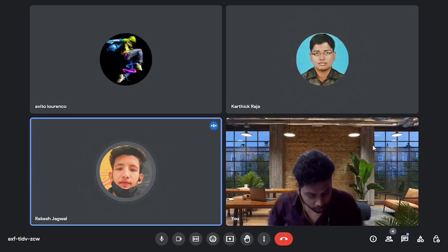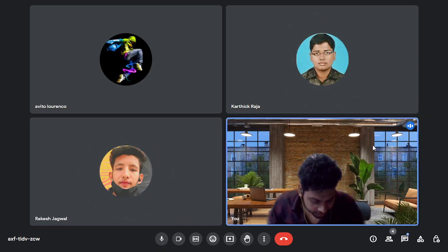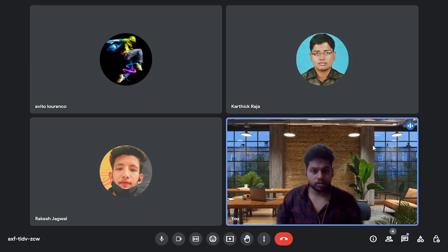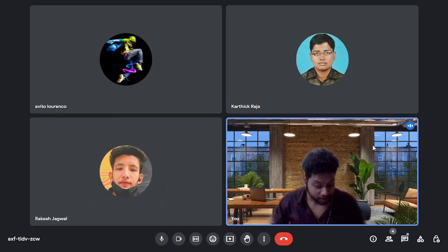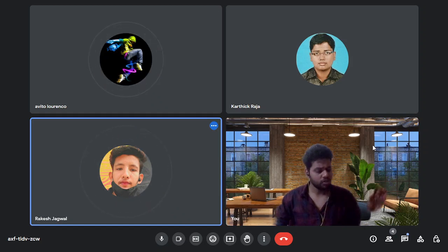Now coming to the question I have asked, let's see what the answer is. I also asked what is the role of a capacitor in an electrical circuit. You said it acts like a tank that stores energy. A capacitor is a passive electronic component that stores electrical energy in an electric field between two conducting plates. In an electrical circuit, a capacitor can be used to block DC current, filter out noise, smooth voltage fluctuation, and store energy. Filter out noise, same concept.